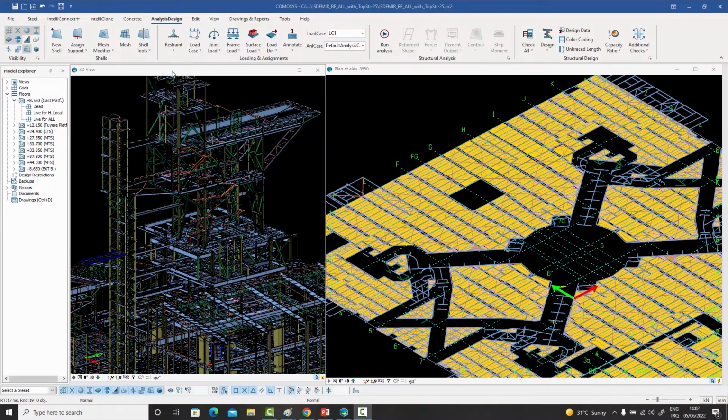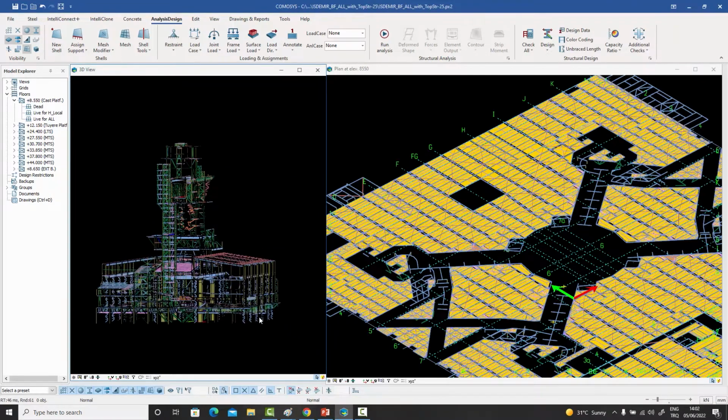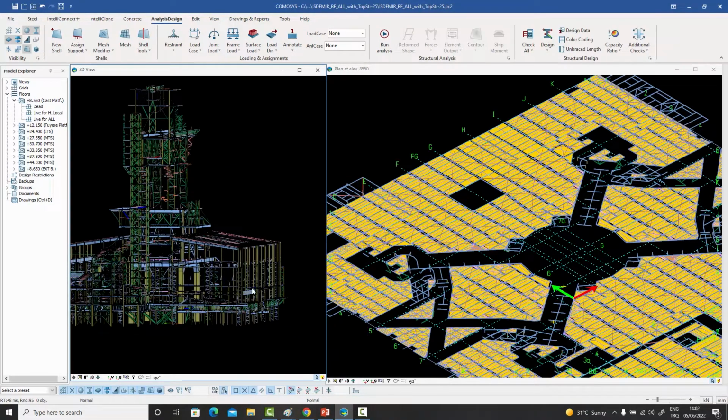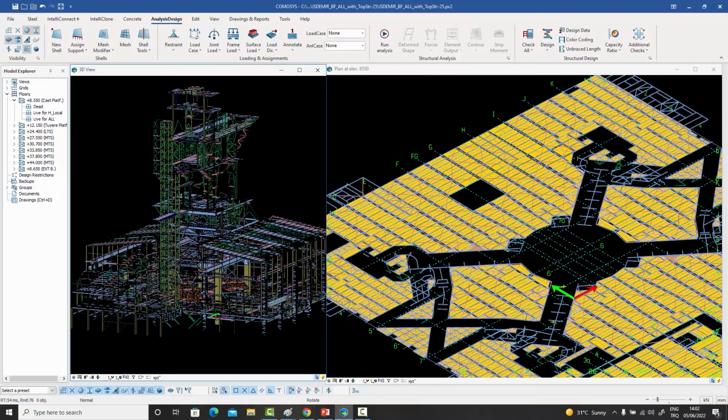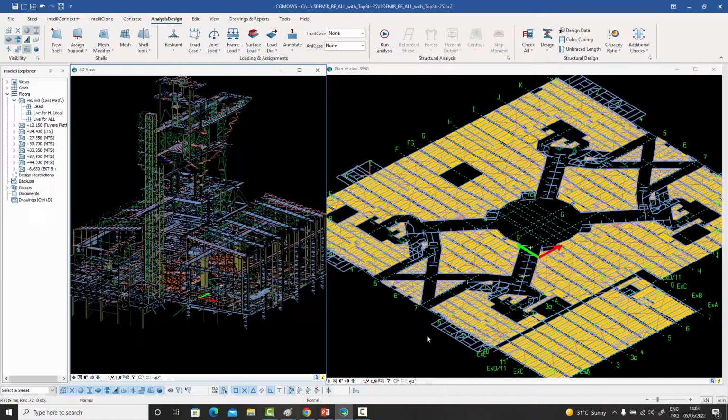Now, if you were doing an earthquake analysis, say based on the equivalent static load method, what you would do is find the equivalent static loads at each floor level and apply them as horizontal loads on, say, the columns directly at certain node points, and that will give you the overall impact of the equivalent static loads on the foundations and on the braces, etc. But we know that in reality, the earthquake loads actually stem from the accelerations of the mass inside the floors. So it's not correct to just assign them to the columns directly.